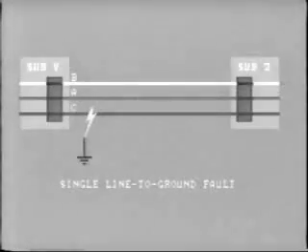Notice that we have broken the traces to indicate where the waveforms just repeat themselves. After 3 cycles of pre-fault recording, we see the onset of a single line-to-ground fault. This fault was actually caused by a tree falling across one of the phase conductors. The tree provides a path to ground.